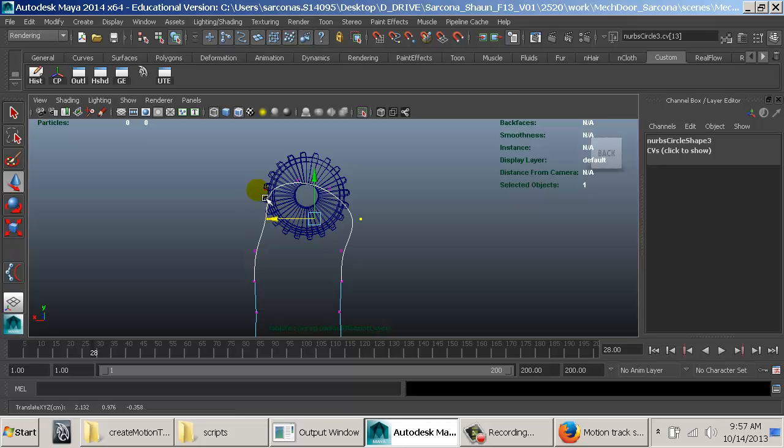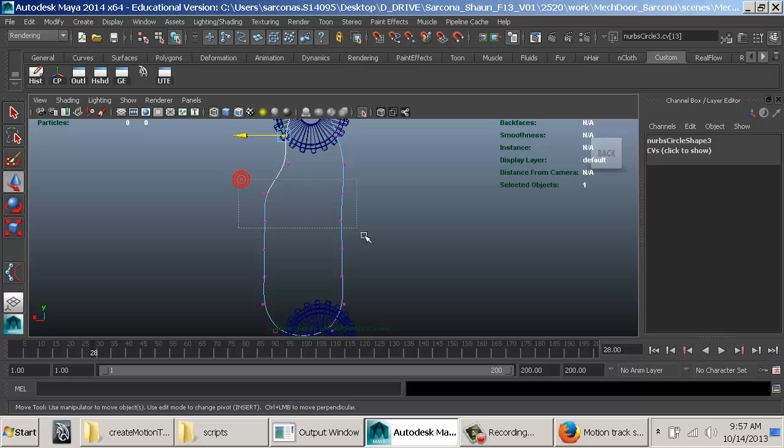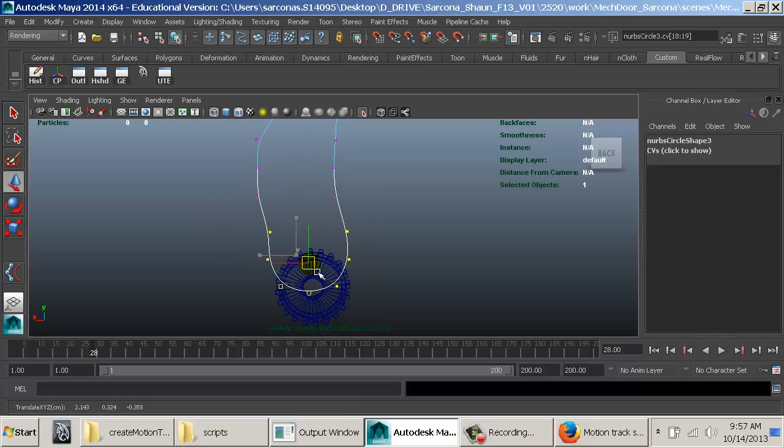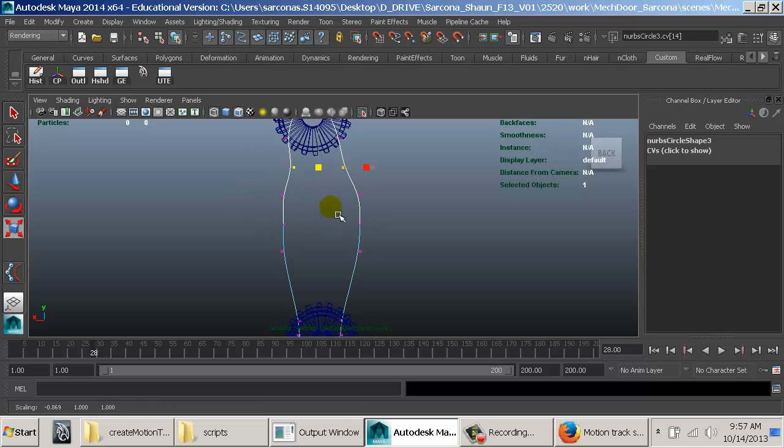Okay, and this is all stuff you want to have set up before you actually create all the curves. Okay, so I actually want to create my curve, get it lined up in this area exactly where I need it to be, and then I can go through and play with the IK spline handle tool settings and all that. Okay. The workflow that I'm showing here is just, I showed the example and then I'm trying to position it. You actually want to get all the stuff in position, get the size of these tracks done first, and then go through and do your IK spline in order for everything to connect.